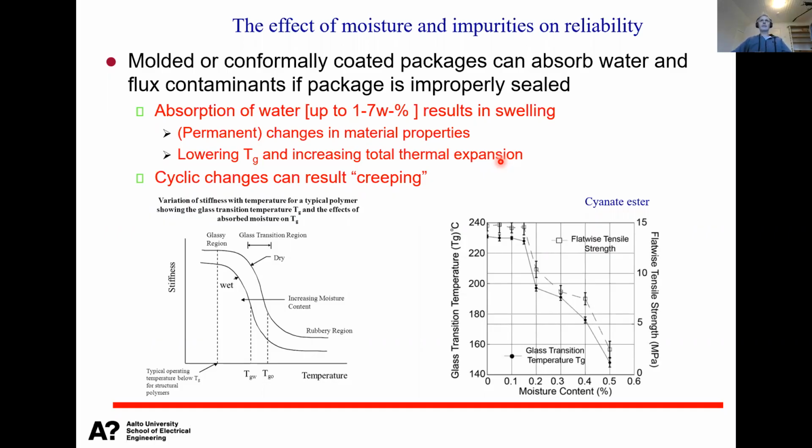It means that there's quite a lot of space for water to penetrate inside, so these polymers absorb water, and we are talking about several weight percentages. And if this amount of water is inside the polymer, then it changes the properties. And these can be either temporary changes, or quite often they are permanent changes, meaning that even if we dry the polymer, it does not recover back to the original properties.